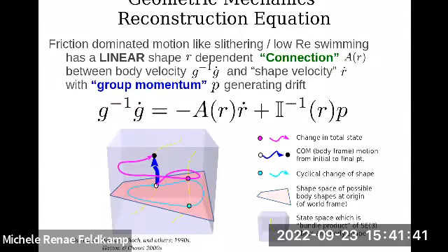Okay, the symmetry reduction, especially when the momentum falls away, which is what I'm going to talk about next, throws away a lot of complexity and relates velocities to velocities without the need of force as an intermediary. And when does this become important? Primarily in motions that are dominated by friction, where this momentum term dies away quickly. So if I'm moving in a regime where the moment I stop reshaping my body, I glide to a standstill very quickly, I don't build up momentum, this term is gone. We don't need forces at all. It's an entirely geometric motion.